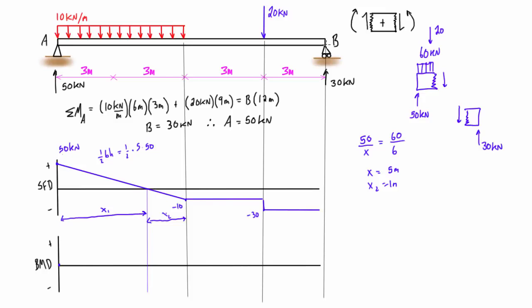We know that this is a beam that has a bending moment of 0 at the end, because it's not a rigid connection. These pins can't build up any internal bending moment like that. So the beam starts at 0 and ends at 0. And in this first section, from 0 to x equals 5, the increase in magnitude is going to be this area, which is 125. And these are in units of kilonewton meters, and up here these were units of kilonewtons. Cool.